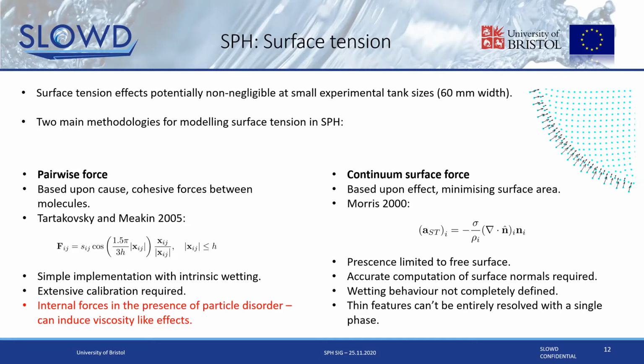So instead we use a continuum surface force. This is where we compute surface normals and calculate the curvatures and then the resulting accelerations from these.